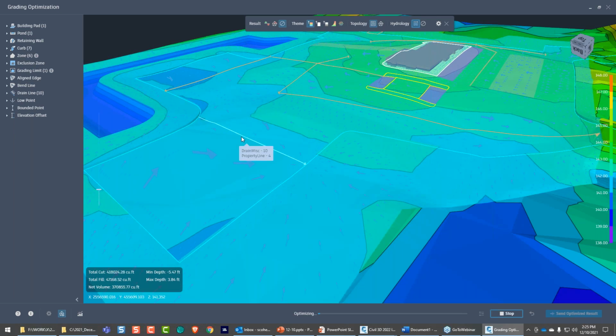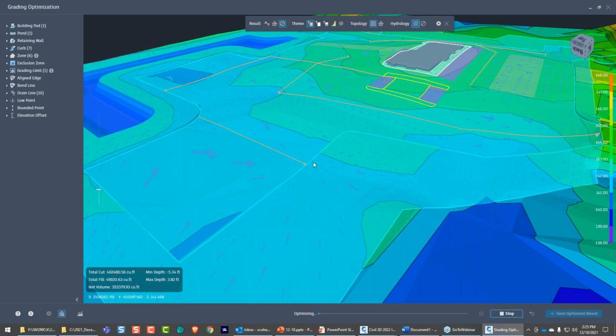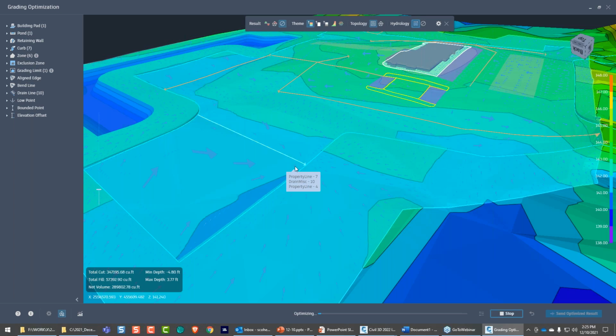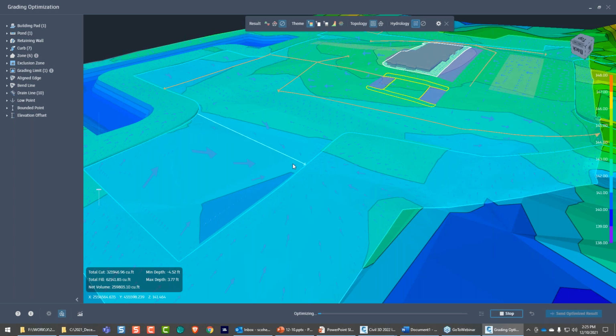So I basically can realize, okay, maybe I just put the catch basin over here, let this thing drain. It's less cut or fill. Of course, you have to work out the numbers as far as what's cheaper. Is it cheaper to get the DBI? Is it cheaper to do the cut and fill? Depends on how your quantities are set, right? But this is letting me know, hey, you've got a low point as this ties in, maybe just put a DBI here and pipe it down to here and not worry about grading this whole thing down. That said, I could just cut this whole thing out and I'm going to just drain it anyway. But that's basically just letting you know how the site's going, all right?